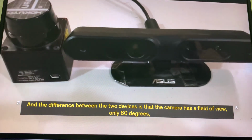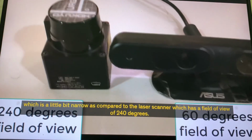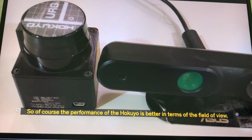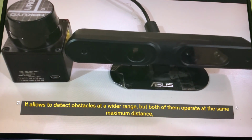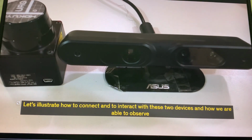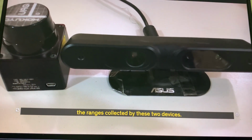The difference between the two devices is that the RGB camera has a field of view of only 60 degrees, which is a little bit narrow compared to the laser scanner, which has a field of view of 240 degrees. So of course the performance of the Hokuyo is better in terms of field of view. It allows detecting obstacles at a wider range, but both of them operate at the same maximum distance, which is around 4 meters. Let's illustrate how to connect and interact with these two devices and how we are able to observe the ranges collected by them.